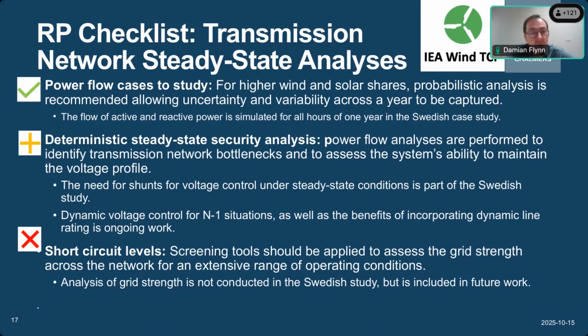Okay, and Lisa mentioned earlier that you're looking at a target of 50% average VRE and maybe 75% instantaneous VRE. So have you thought about grid strength and short circuit levels and things like that? Yes, absolutely. However, we have not yet started this work, so this will be our next work in line after we did this n-1 analysis for the dynamic reactive power requirements.